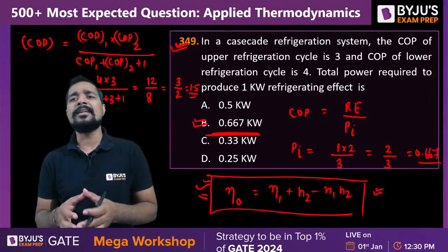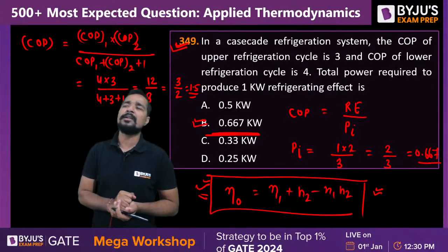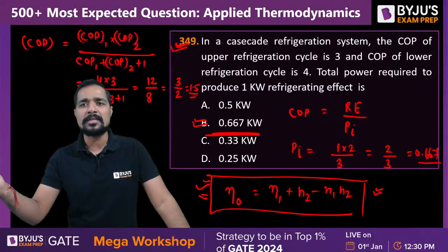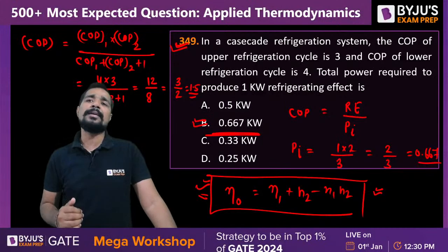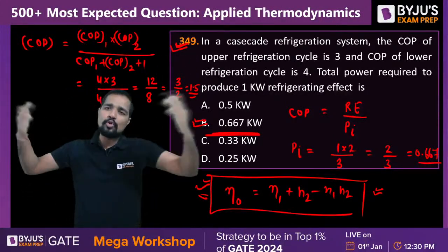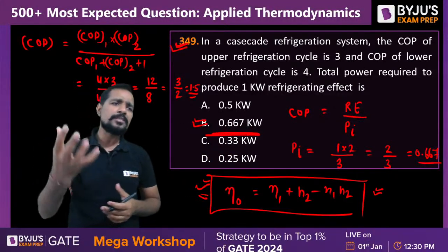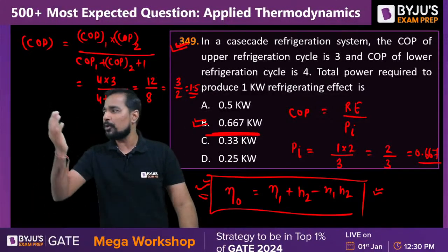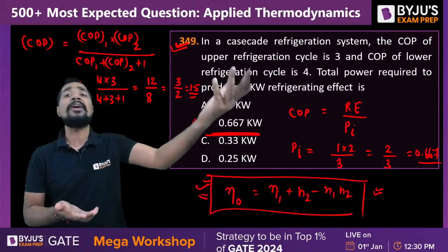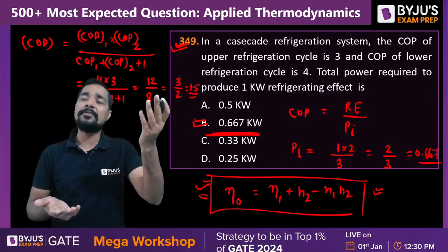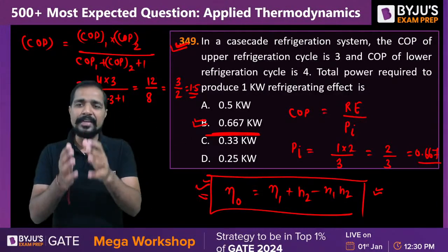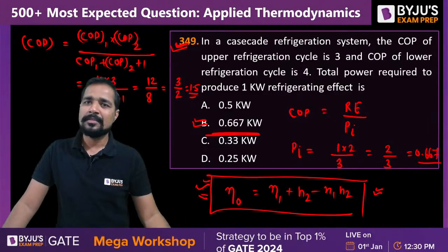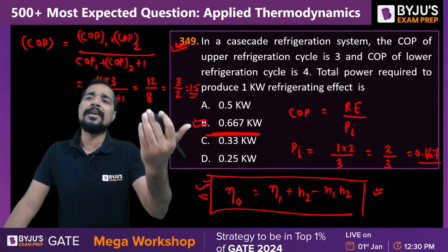Yeah, these are the industrial refrigerator. These are generally used, let me tell you in advance, when we are dealing with the cryogenic refrigeration system. When you are dealing with the temperature lower than -100, -180, -170, then in that condition, my dear, temperature difference between the atmosphere and the lower temperature body is so much high. So when you will deal with this single refrigerator, then compressor has to do a lot of work that is near to impossible, because the difference of the temperature is very much high. Means you are just taking the heat from -100 degrees centigrade and you want to reject this heat to the 35 degrees centigrade. It's quite difficult. Temperature difference is near about 135 degrees centigrade. So in the compressor, it is very difficult to achieve this temperature difference, my dear. That's why we are using such a refrigerator which can fulfill the requirement in 2, 3, 4 cycle, my dear.